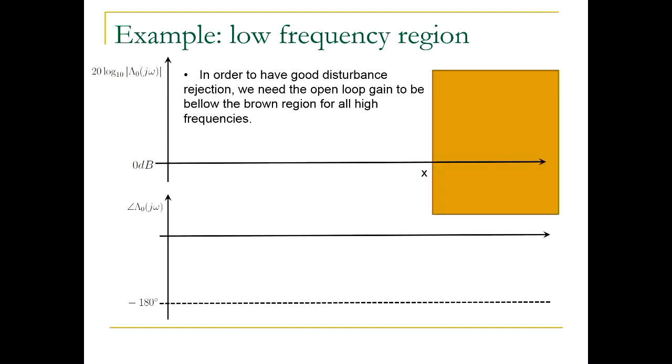So that's what we get. We have basically a region, this box. You tell me, or your boss tells you, for which frequency range you want to be robust in terms of measurement noise. Usually you say for all frequencies larger than this. Then your open loop gain should be sufficiently small in all of this frequency region to achieve sufficient attenuation of measurement noise in that region.